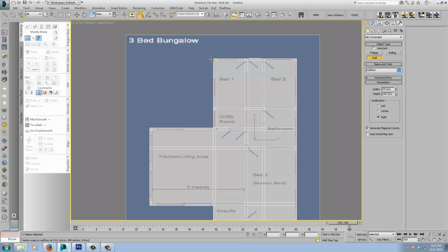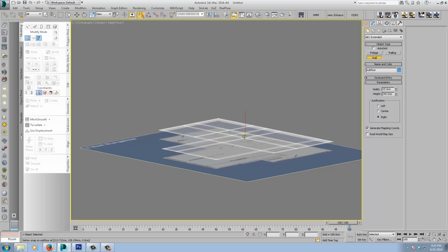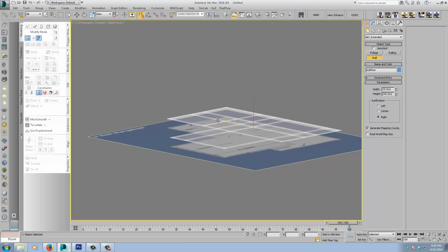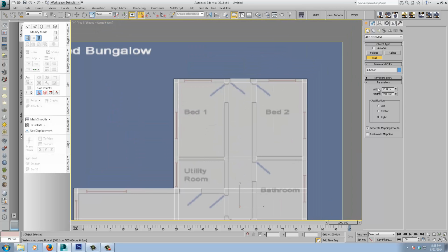Let me start with a wall. Just make sure this is at 0 on the Z plane. Make sure these verts are at 0 on the Z plane when you're snapping the walls, because otherwise it won't find it, because this wall tool snaps by default to 0 on the Z plane, so just be aware of that.